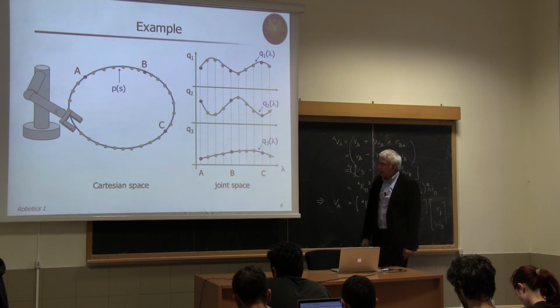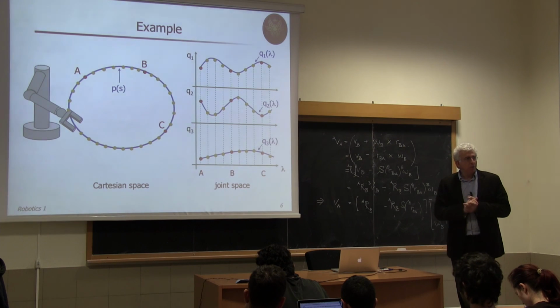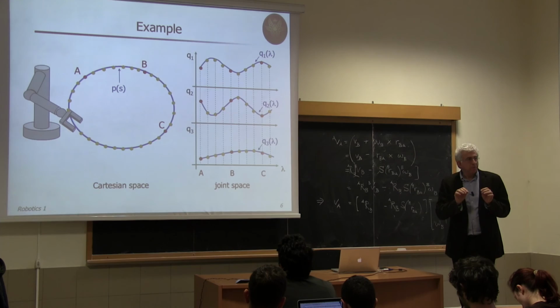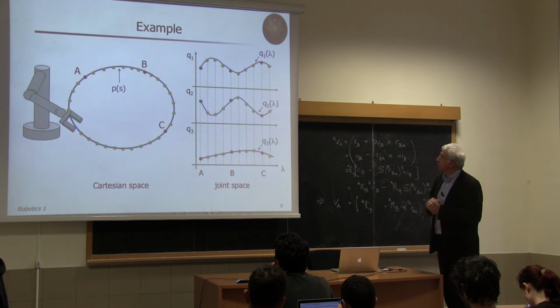So I may interpolate it with some function, polynomials, or linear path in the segmented linear path in the joint space. Again, not good, because this would mean that joint velocity would either jump or needs to come to 0 at each knots in order to not have this discontinuity.